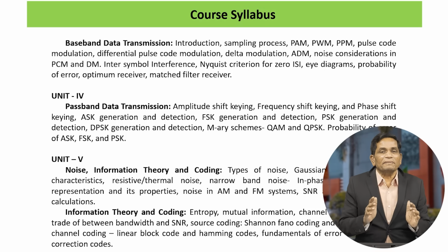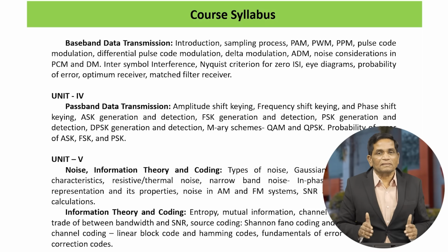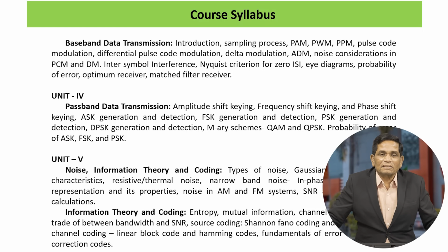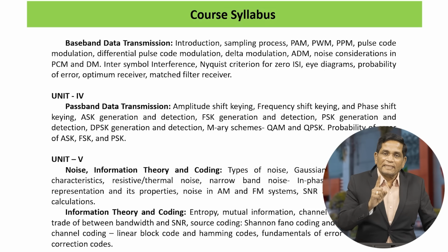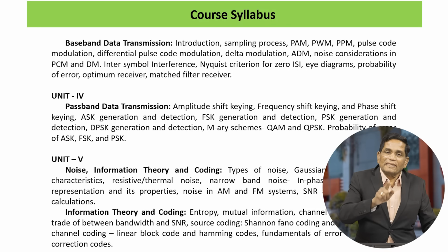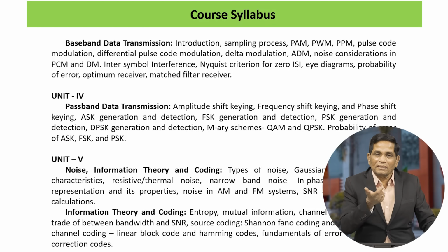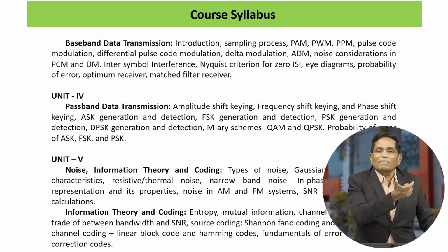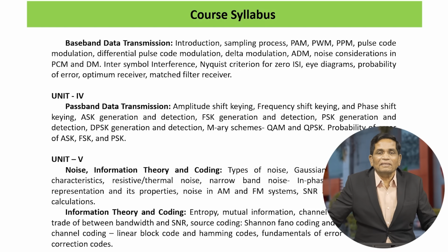But if you want to transmit the binary data into free space, you use passband data transmission. Fundamental techniques are ASK, FSK and PSK, same as AM, FM and PM. The only difference is that the input to the modulator there is an analog signal, but here the input to the modulator is binary data.